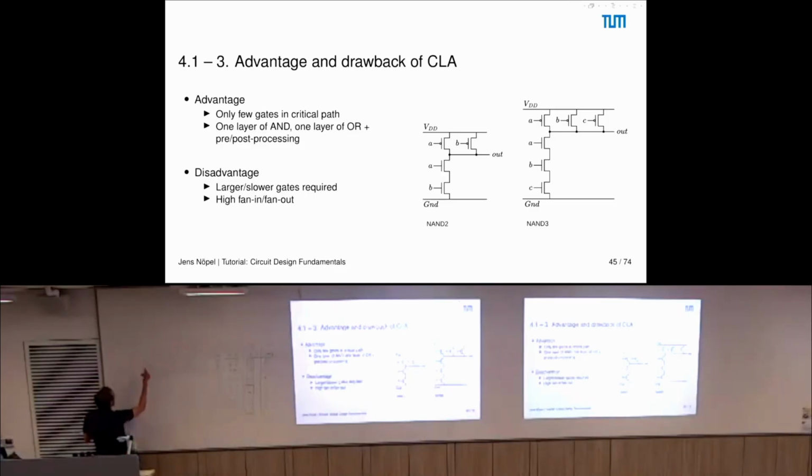So let's draw a simple inverter, right? This looks like this. I guess you've seen that before, right? Yes, perfect. So this one is our PMOS transistor, and this is our NMOS transistor. Have you had a lecture regarding how such a transistor is built up? Yes? So you know that this is silicon, that then an N or P well is added to those, right?